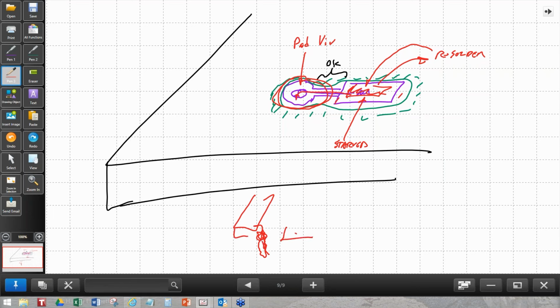But the other surface mount pad, if that pad has been completely soldered, then theoretically there wouldn't be much wicking as long as this trace is short, because that pad is already full of solder, and the solder would have come up and flowed partway down that pad. Of course, if that pad is very long and it's already soldered, then the trace itself could take enough solder off of the pad that you would have a problem. So, all right. Thank you very much.